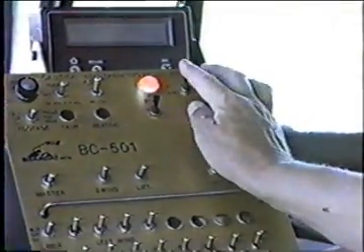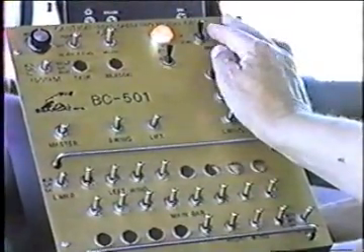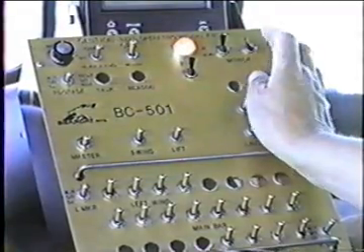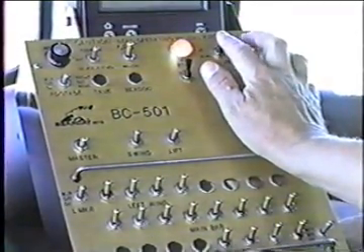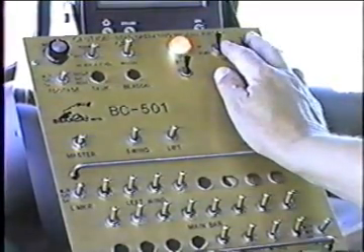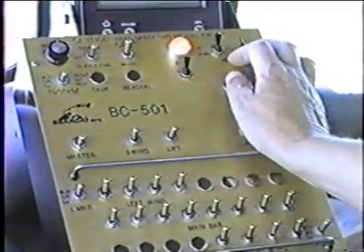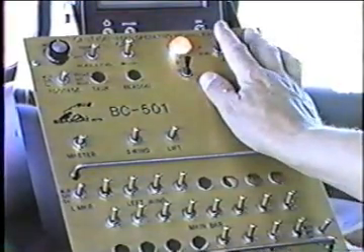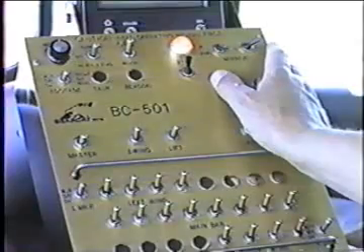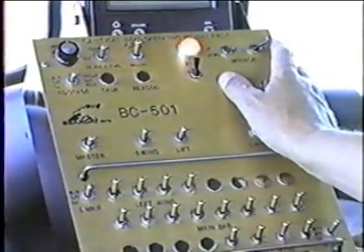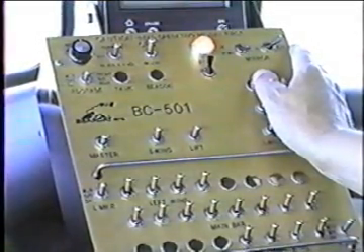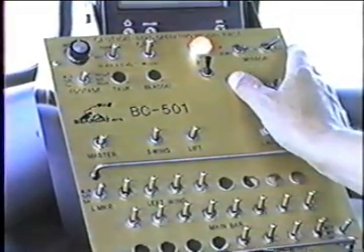Mirror, up, down, and in and out. Just as it's marked, the up position and in position is the normal go down the highway setting. That is, for normal highway driving, you would adjust the stops on the mirror for the up position and the in position. The down position and out should be adjusted so that the end of the wing of the spray bar is in the center of the mirror for your driving position, so that you can pay close attention to the end of the spray bar when you are spraying.